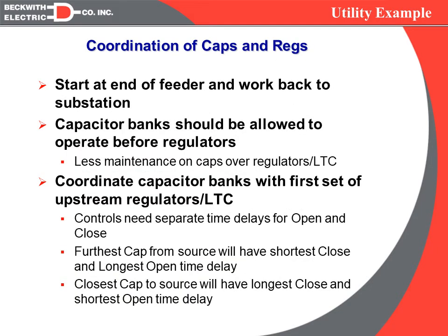So, we're going to start at the end of the feeder and work back to the substation. The cap bank should be allowed to regulate or operate before the regulators, so therefore we need the cap banks to have the shorter time delays. And we're going to coordinate the cap banks with the first upstream regulating device they encounter, whether that's a line regulator or whether it's all the way back to the feeder regulator or the LTC.